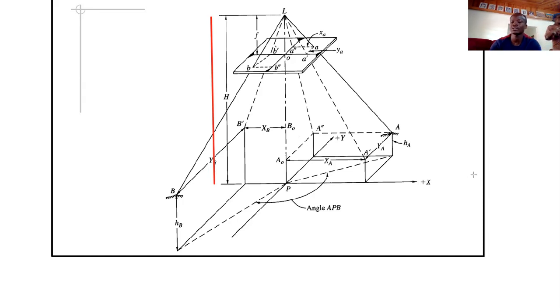If you've actually worked on a construction site before, you know what I'm talking about. So an assumed datum, that's what we want to call it. Doesn't matter what you call it, but there's always a reference, an imaginary surface from which all measurements are done.